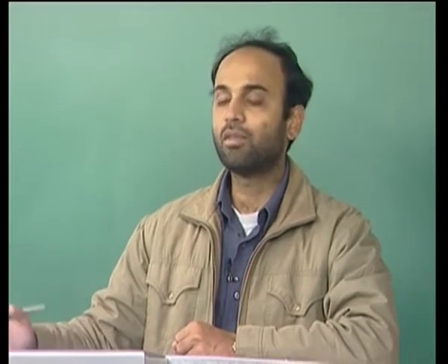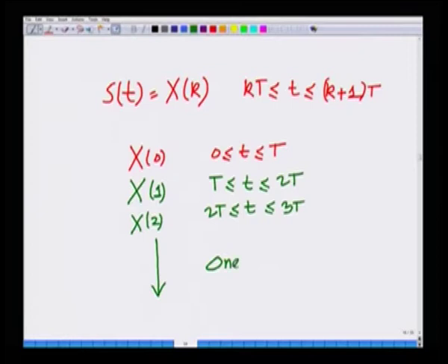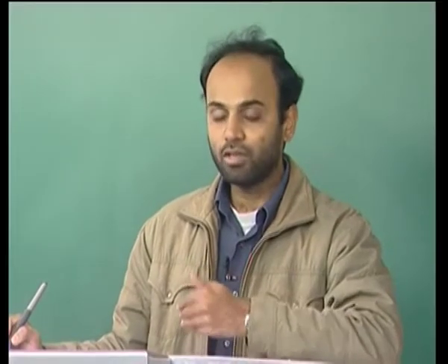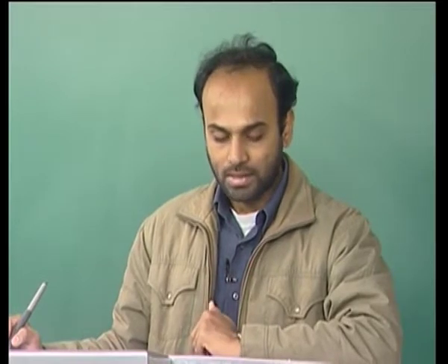that is, as we said before, one symbol every T seconds. So, you are transmitting one symbol every capital T seconds, and T itself is equal to 1 over B. That is essentially the principle of a single carrier system, and the rate is obviously 1 over T, which is B symbols per second.